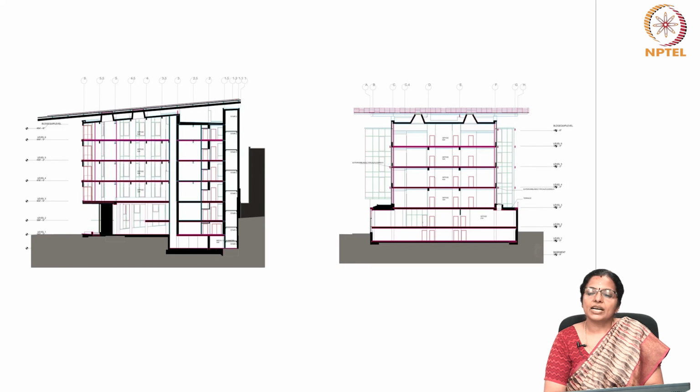This means considering the conditions for all the 8,760 hours of the year and having an understanding of how day and night temperature swings happen, the rainfall patterns, the cloud cover, and the hourly availability of the sun, wind, and light. After that, one must make informed decisions about how to approach the project. First, let us look at the strategies that were followed in this design.